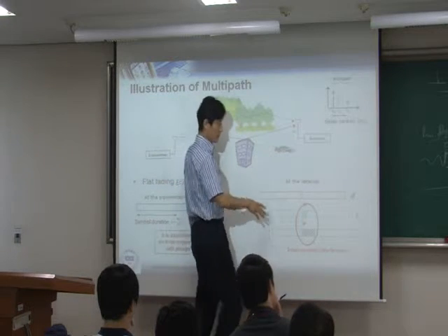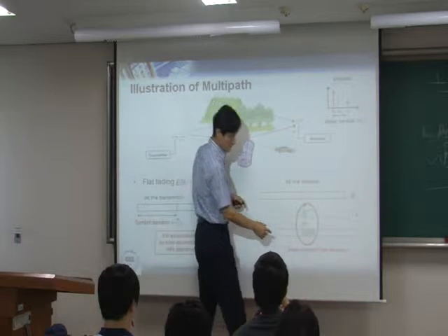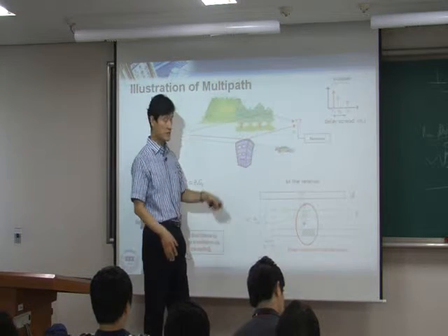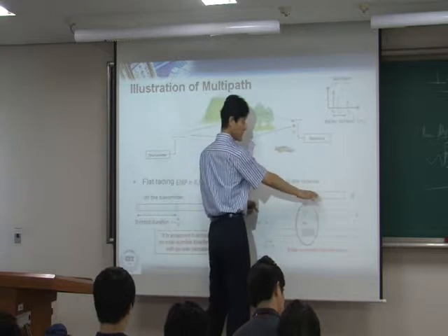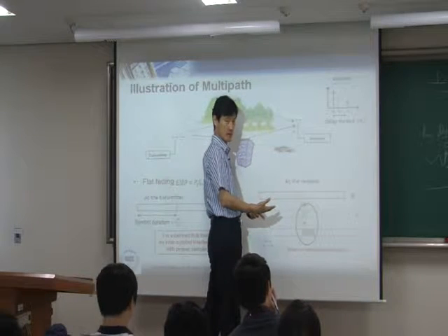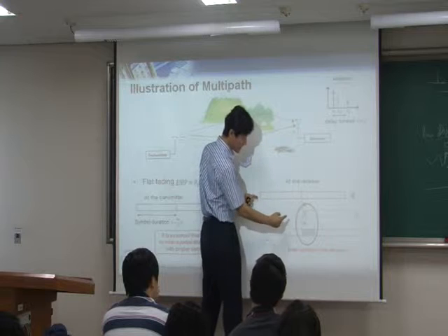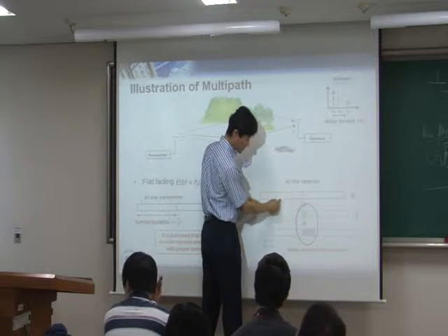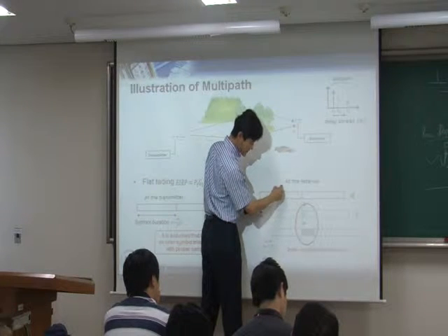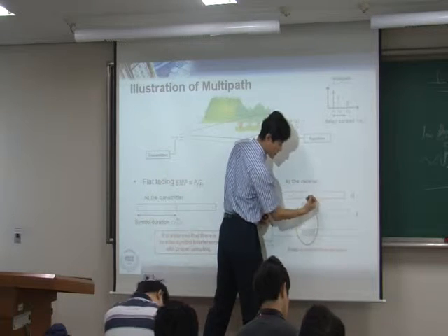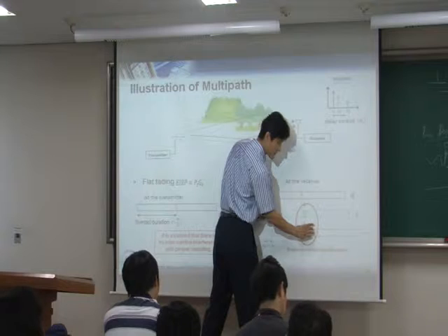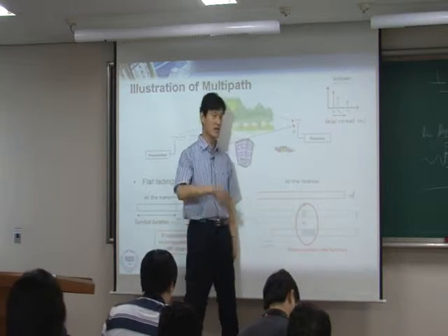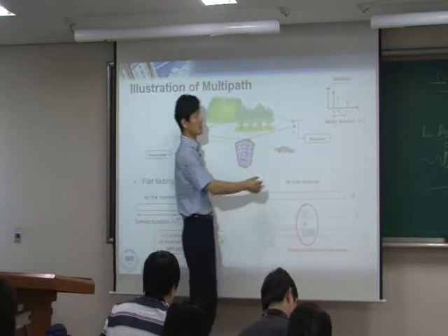In this kind of scenario, inter-symbol interference is very bad, of course, right? But this happens, and still it's okay. Why is it okay? Because in the receiver, you receive this whole thing, and eventually you do sampling, okay? When you do sampling, most likely you sample somewhere in the middle. This is one symbol, you take a sample at this point, or maybe somewhere around this point. Since you pick a sample right here, and also right here, to recover the first symbol and second symbol, this inter-symbol interference is pretty tiny. So I can recover the first and second symbols with no problem. This inter-symbol interference does not affect your performance, because the delay is actually pretty short.